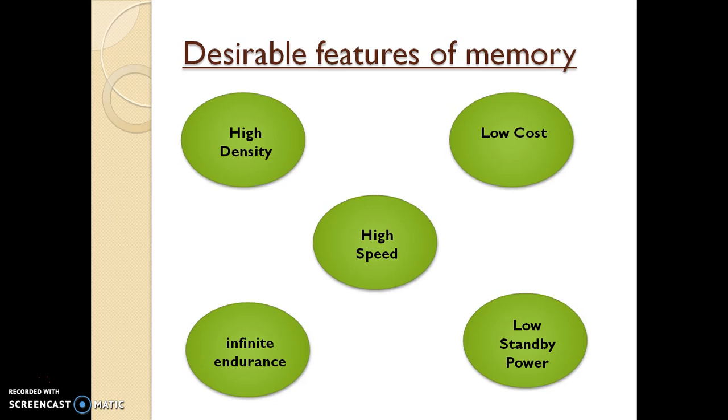Unlike semiconductor memories that use electron charge to store data, MRAM uses electron spin, and unlike charge, electron spin is inherently permanent. MRAM has been called the ideal memory because of its potential to combine the speed of SRAM, the density of DRAM, and the non-volatility of a flash.